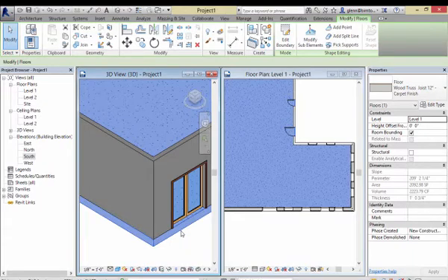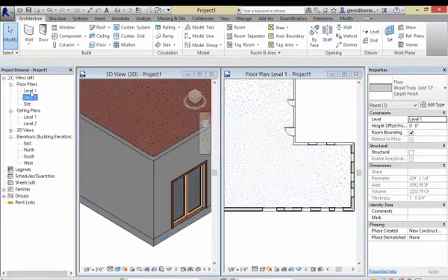Now, when you place a roof, it's going to look just like placing a floor. But we're going to start worrying about what level we place it at, because the floor was going to be at level 1. The roof we typically like to put up at level 2 or a higher level. So when we draw it, we could really draw it on any specific level, but ultimately we'd like it to be hosted or live at level 2, in the hierarchy of the objects. The way we make that happen is we can just double click on level 2.